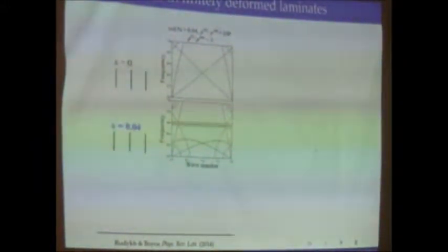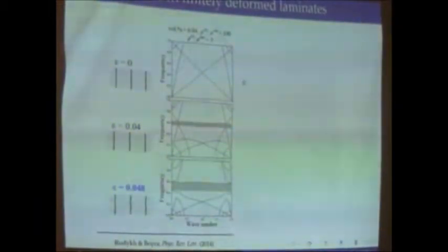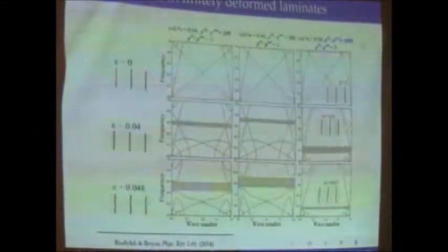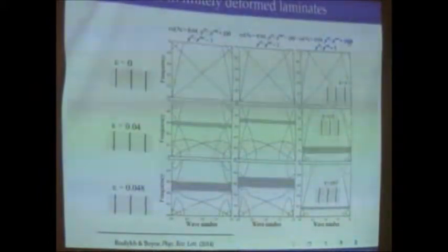In that way, we obtain a band gap in situations when we didn't observe anything in the undeformed state. And then we can continue deforming the material and obtain these band gaps. You can obtain this phenomenon of inducing band gaps by deformation and instabilities in polymer composites with similar or identical densities, and you can obtain similar behavior also for different stiffness ratios and different wavelengths that you induce by your instability.